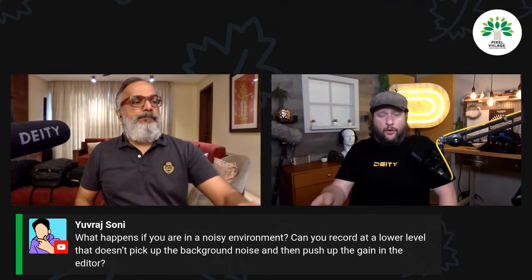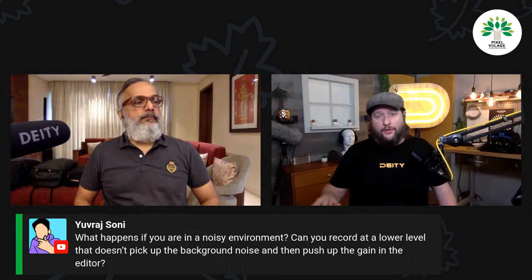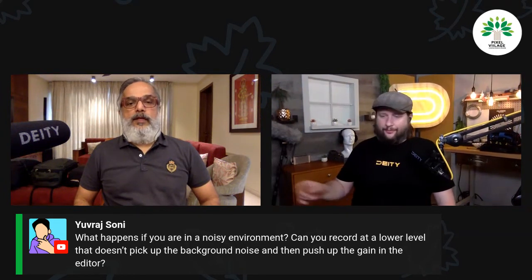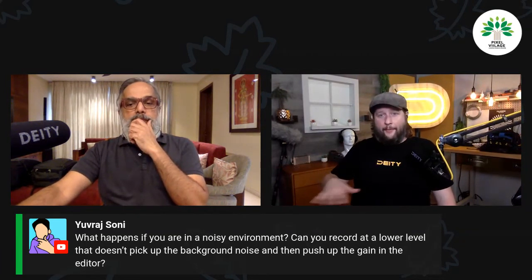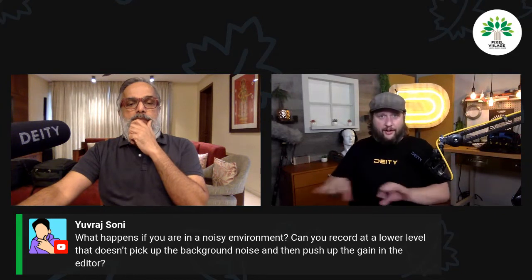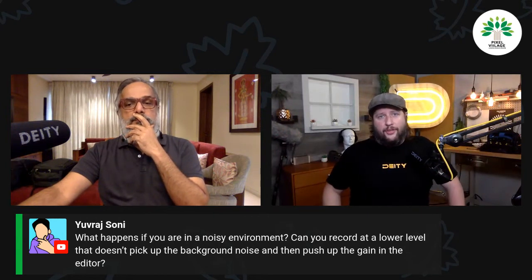What I would do is not just add gain. I would actually run something called a compressor. That way it's only adding gain to your peaks, so it's not going to add too much gain to the self noise, the background hum of the ambience around you when you're recording. The second thing I would immediately do is add a noise gate. That's going to cut off anything below that threshold. So I've got the background noise only when my voice has been boosted, but when no one is talking, there's nothing there. And then once I add in the background music I want, it sounds perfect.